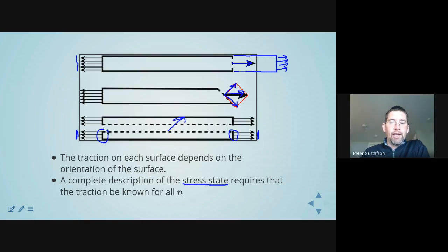What we're doing here is saying all of the forces on this lower body, and I'm now going to draw a box around this entire body, have to be in equilibrium. We know the boundary condition here, and here, and on the bottom it's got to be 0, and if we sum up all of those forces, the boundary condition on the top also contributes to the forces, and force balance drives it to 0 in this case. All right, thanks.